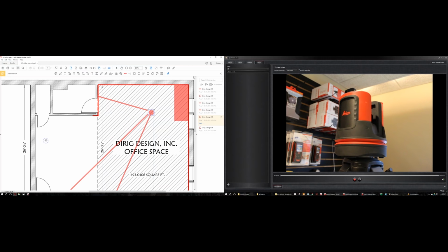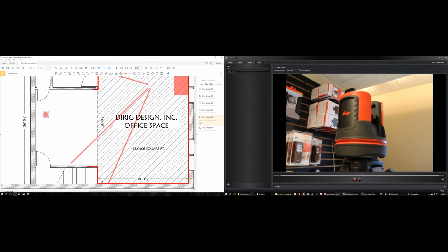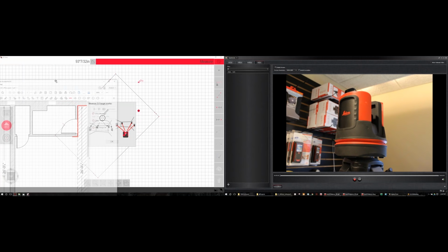and then I move this Disto from here to here, it's not going to work because the Disto cannot see this point and it cannot see this point. It might be able to see that point, but what you're going to want to do is take 3 points that you can visually see from both areas of where you want to locate it. Unless you don't care about relocating it and you just want to secure the location of the Disto. That's really the thing you've got to think about, being able to visualize these points.